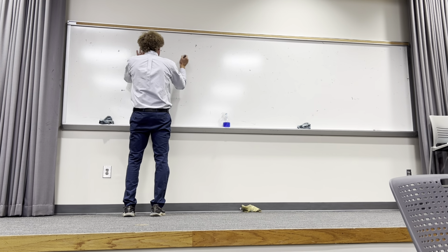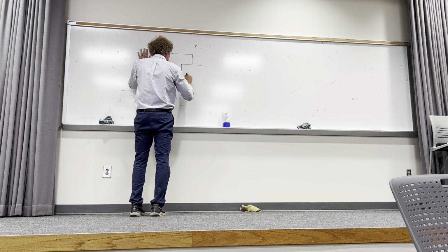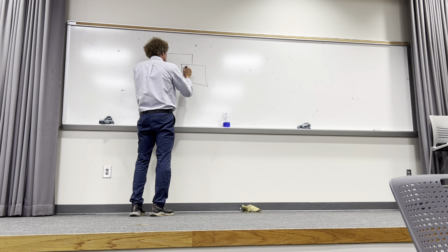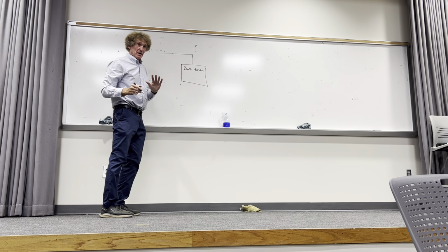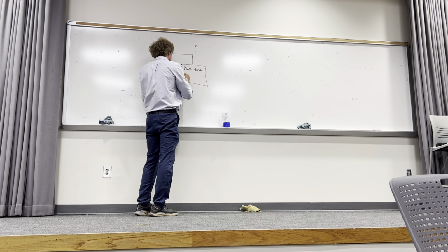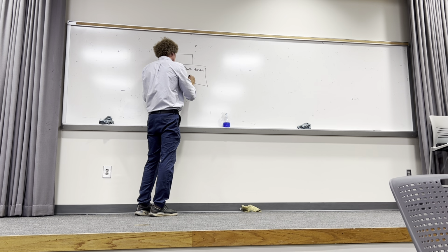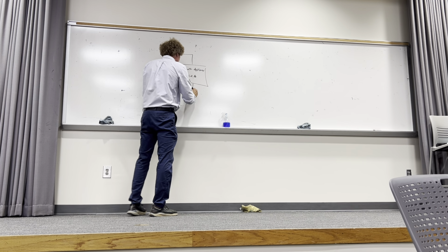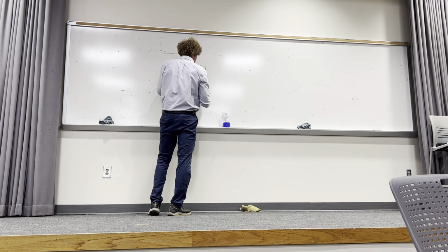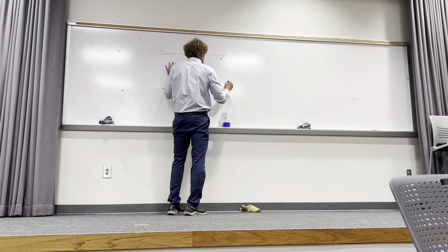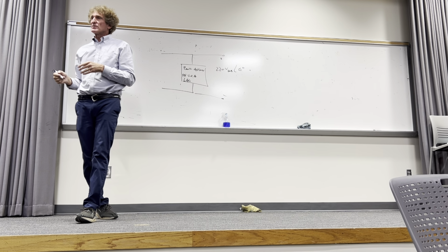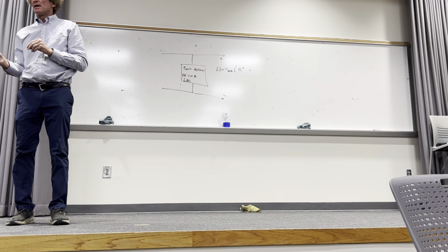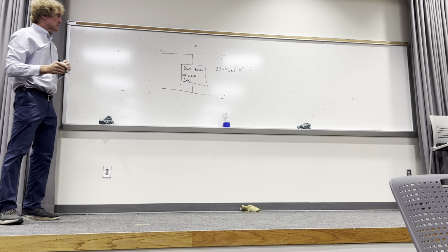What they had was a load, you tell me if I'm wrong about this, but they had the actual average power be equal to 40 kW, is that right? And then they set a power factor of what? I know it's lagging. 0.8. Of 0.8, it's lagging. And then they had a voltage across that of plus or minus 220 volts, right? That's RMS. Always put this at 0 degrees unless they say it's not. Always assume it's 0 degrees. Y'all with me, class? Don't ever make the problem more complicated than it needs to be.